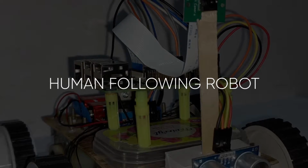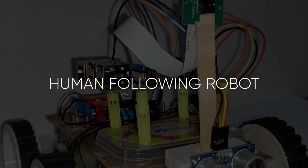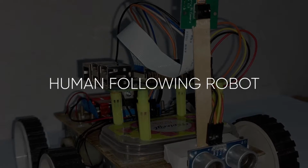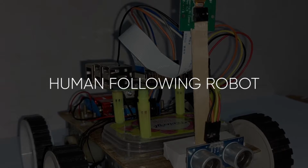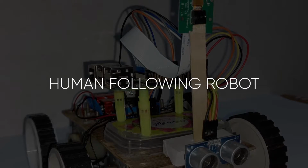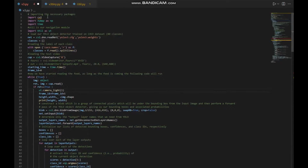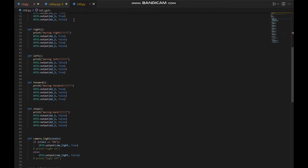So we have developed a four-wheel robot that is based on computer vision, where the robot visualizes the surroundings by the frames fed into it through the camera, and then with the help of sensor fusion and a navigation model, our robot moves in the real world, avoiding any obstacles that come on its way. In the beginning, we are importing the necessary packages, which are OpenCV, NumPy, Time, and Util. Util is basically our navigation module, which is used to give commands to Raspberry Pi, which in turn will control the motors and control where the buggy will go. Here is the Util, our navigation module.